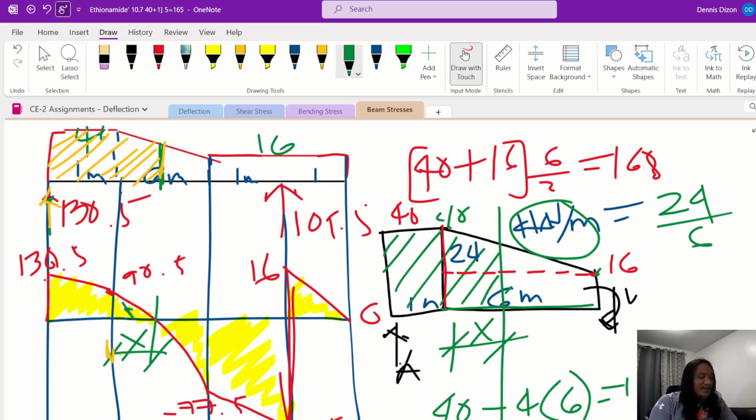What I usually do, and even our professor at St. Joseph College in Masin, is just locate the zero shear. If it is complicated, just sum up the forces vertically, and determine the distance x where the reaction versus the load is 0. You can probably solve the area, but why would you punish yourself?